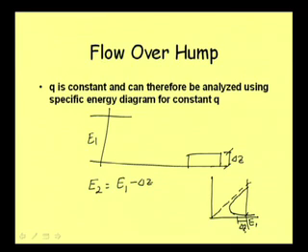If we reduce the energy by delta z amount, then originally if our depth was this much and it is subcritical flow, it will come to this one. So, if y1 is the depth here, then y2 will be the depth here. So, depth is coming down, and over the hump also the depth will be coming down like this.